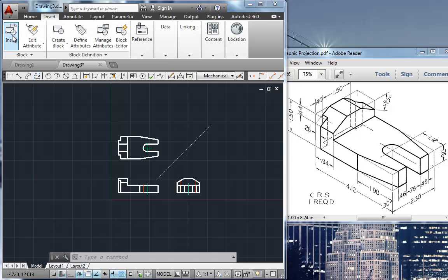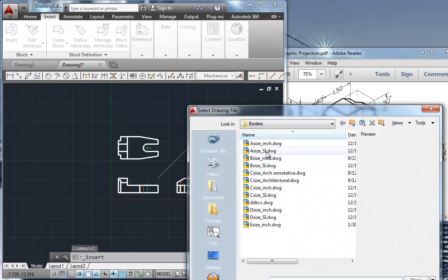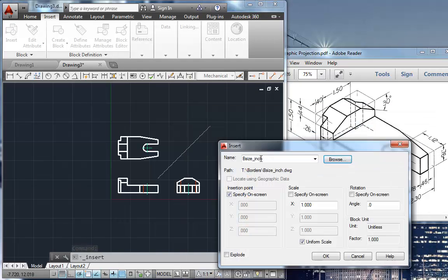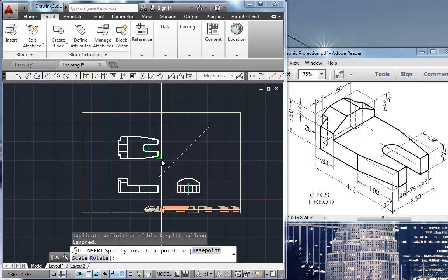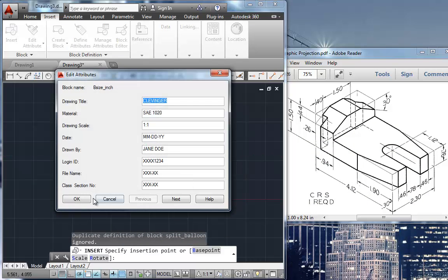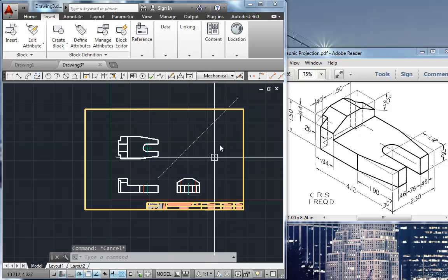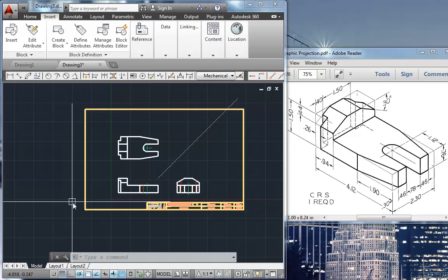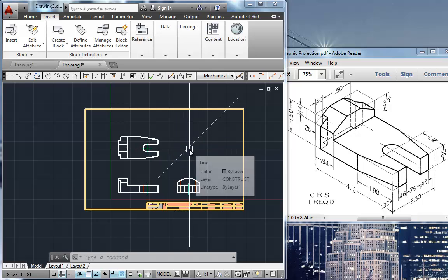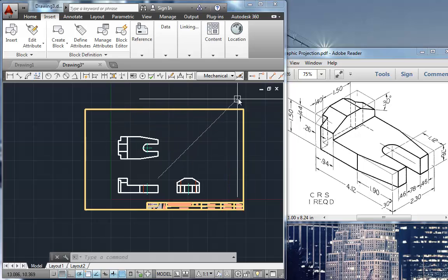So we'll insert, B size inch. When you drop that in, if by chance on a particular problem, that miter line was sticking way out of the border, trim that off. It'll screw up the print because it'll compute the wrong size for the drawing when you go to print. So if your miter line sticks way out of the border, you don't have to keep it. You can erase these if you want. If you keep it, put it on the construct layer and make sure to trim it off to the border if it sticks out. Okay.